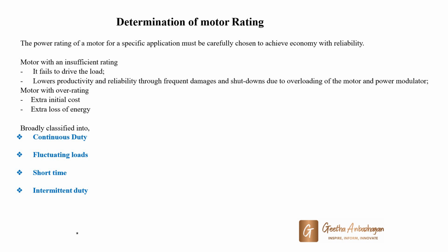In conclusion, the power rating of a motor is a critical decision that shouldn't be taken lightly. The consequences of using an insufficiently rated motor include inefficiency, frequent breakdowns, and reduced reliability. On the other hand, opting for an overrated motor results in unnecessary initial expenses and energy wastage.